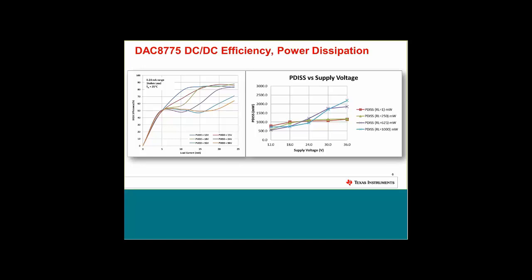And this is power dissipation on our board, of course, not counting the power dissipation across the 1 kilo load. In the end, it's about 750 or 780 milliwatts, but only when operating from a 12-volt supply voltage. And as I mentioned before, we could see 12 to 36 or potentially even 40-volt input supply voltages.